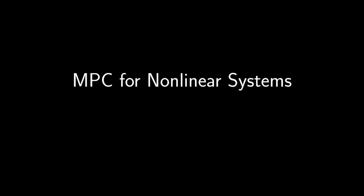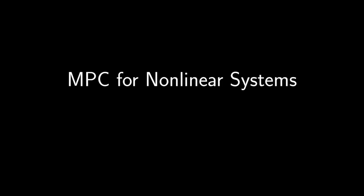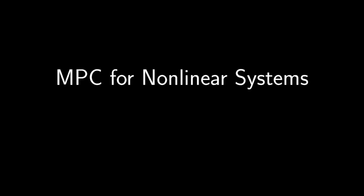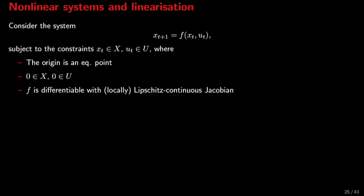Hi and welcome back. In this video lecture, we'll give some MPC design guidelines for nonlinear systems. We start by considering the nonlinear system x_{t+1} = f(x_t, u_t). The system is subject to the constraints that x_t must remain within the set X, and the control actions u_t must be taken from the set U.